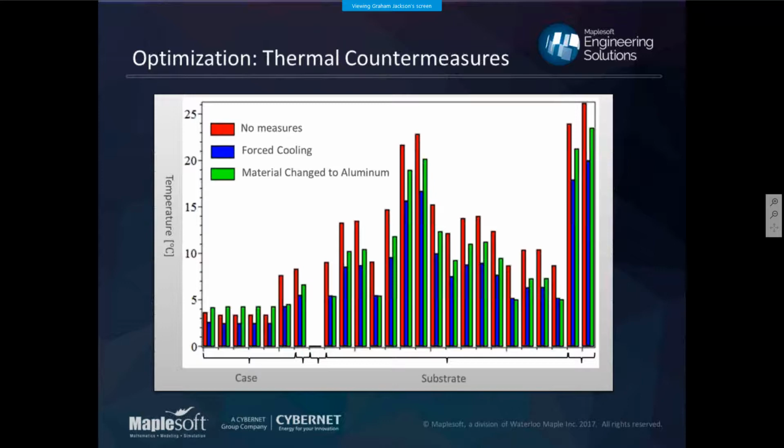So with efficiencies like this, we can even break down our 16-part substrate into 32 parts. We can add a relatively functional level of fidelity for many people's thermal analysis, but then we can make those simulation times so quick that if people are looking to run parameter sweeps to figure out just what sort of material they need or how thick of a material they need to reach their thermal design goals, these things are very possible, and they can happen so quickly using a technique like this.